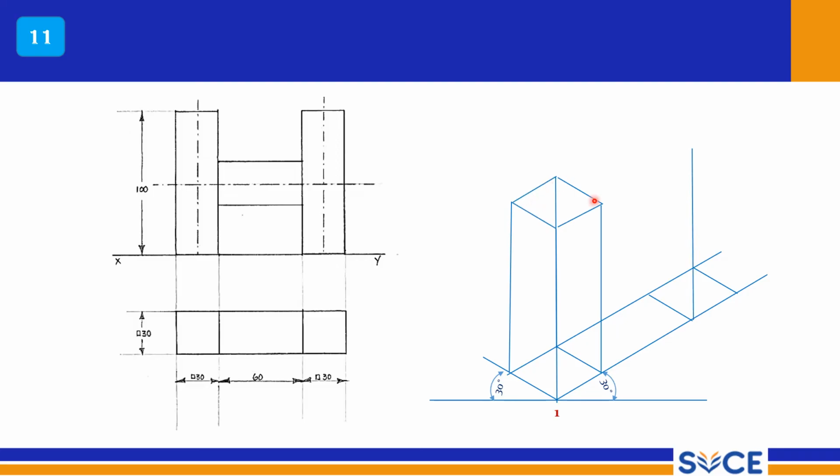You can draw the thick lines, and now this member should be projected at 120 mm, draw this line, right? Now draw the vertical lines and complete this vertical member. Now this is one vertical member, this is another vertical member. In between, from here to here, this height should be measured. So from here to here should be marked.